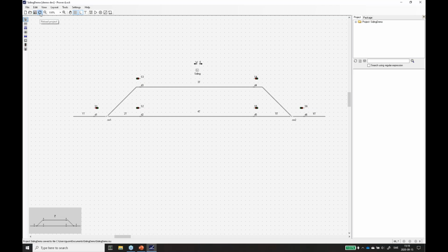And what I have done thus far is simply creating a configuration based on the objects that are defined in our generic application. And all the requirements are still in the generic application. And now I want the tool to create the specific requirements. So for instance, it will now generate all the possible routes according to the rules that we have. And it will generate all the logic requirements for each specific object here. So for each signal, for instance, it will generate specific requirements.